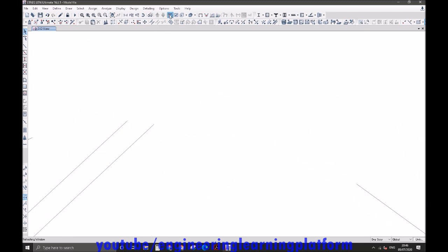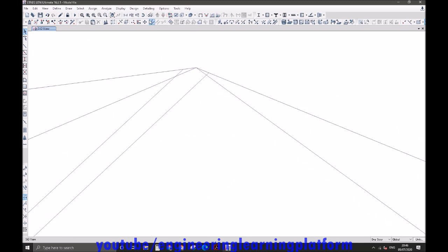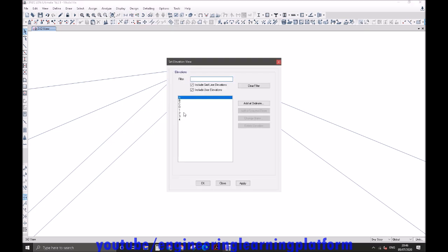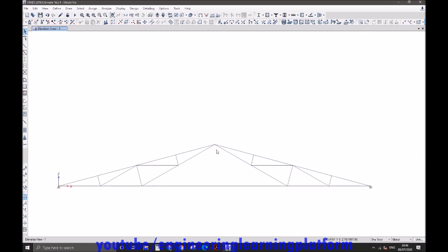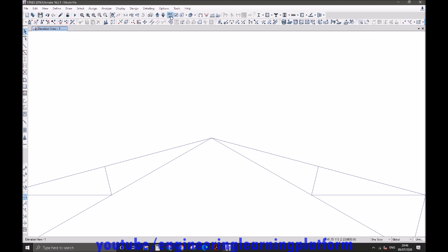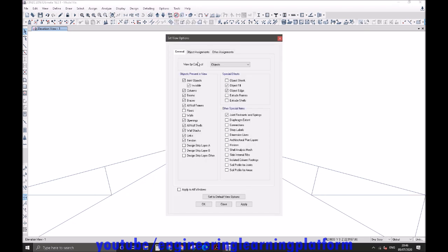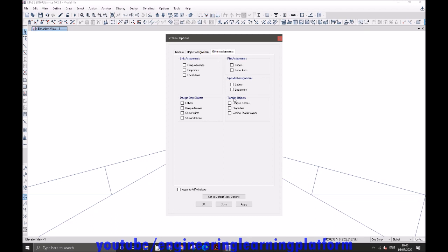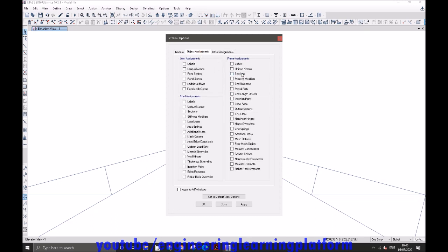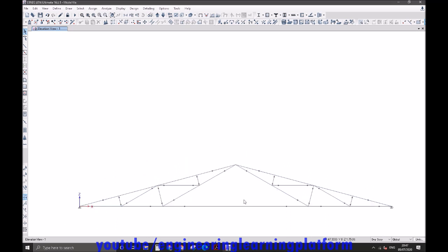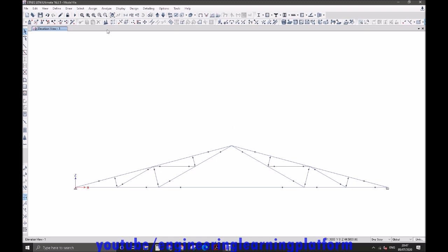So now the members are correctly joined. Let's check whether we still assign the end releases to this point. I'll go and check, turn on the check for end releases. It is usually in frame members and end releases option. Okay, yes, we have assigned the member end releases.